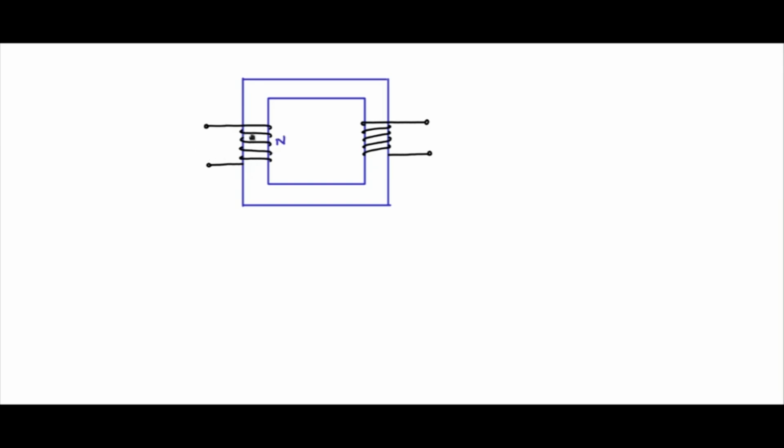So let us say the number of turns on the primary coil, I'll call it NP, and the number of turns on the secondary, NS. I will call the potential across the primary terminals EP, and the current through the primary IP. The MMF which is generated in the primary part of the core due to the primary current flow is NP·IP, and this will force a flux rate dφ/dt to flow through the core.